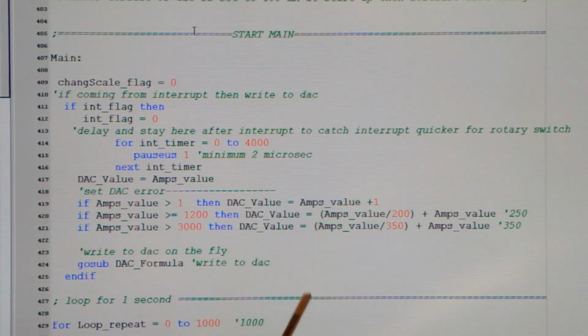So while it's communicating to the LCD screen, the interrupts are turned off. And the reason why you turn them off is that you want to finish the communication part. If you pulled out while you're talking, the message is going to be half done, which means it's going to be an error or corruption, and you don't want that. So once it's writing to the LCD, switch the interrupts off. In most cases, you have to do that if you don't want any errors on your LCD screen.